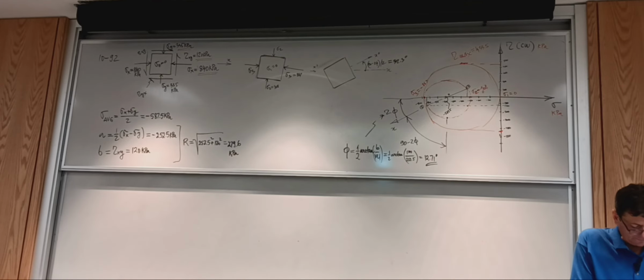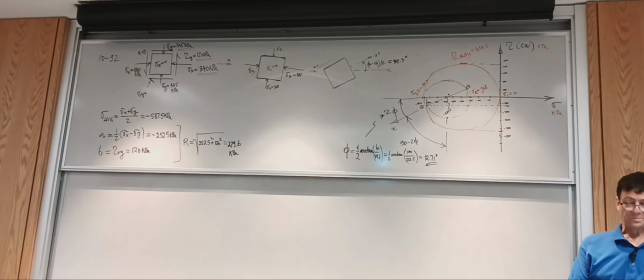An aluminum association standard channel is to be specified to carry the load shown, to produce a design factor of 4 in bending. The legs of the channel are pointing down. The channel is made of 6061 T6 aluminum. For the channel selected, compute the maximum shearing stress.